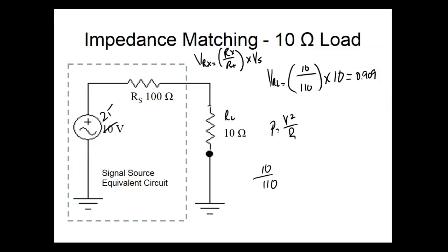So in DC, if I change the voltage on you, you'd go back and redo all the math, right? But in this circuit, this resistor right here will always drop 90.9% no matter what the applied voltage. So we call it the voltage divider formula, and what it does is saves one math calculation.